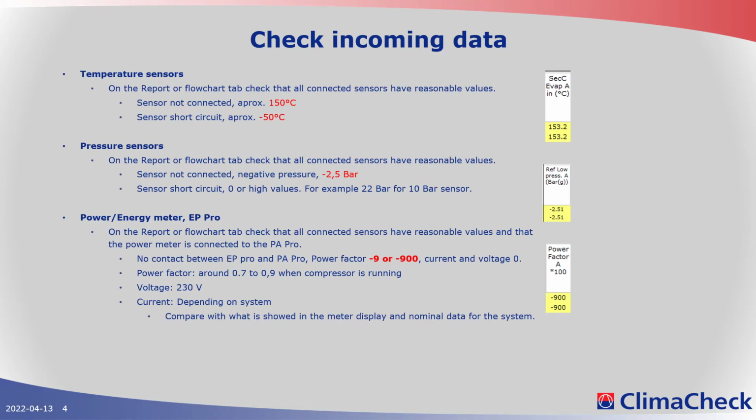The standard sensors are not good to measure negative pressures at all. We have special sensors for below atmospheric pressure. But regardless, be careful, make sure that you check your sensors. Best is, before you apply a pressure sensor to the system, to connect it to the equipment at atmospheric pressure and check that it reads atmospheric pressure plus or minus a few kPa. So pressure sensors are easy to check versus atmospheric.